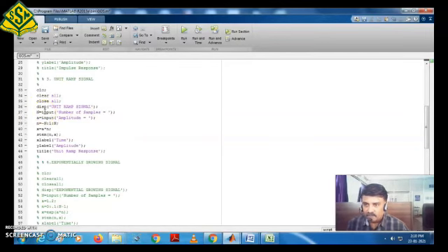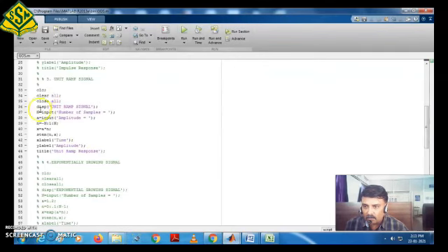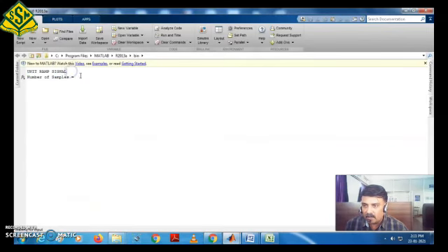Here two input values are taken, and then small n varies from minus n to plus n with a distance of 1, and then x will be a into n. And stem: what is the purpose of this stem? Stem is used to display your discrete values, and the remaining lines are the same. Shall we run? Okay. You will get the unit ramp signal as available in the program. We are going to display your program name, that's all. It is displayed here, unit ramp signal.